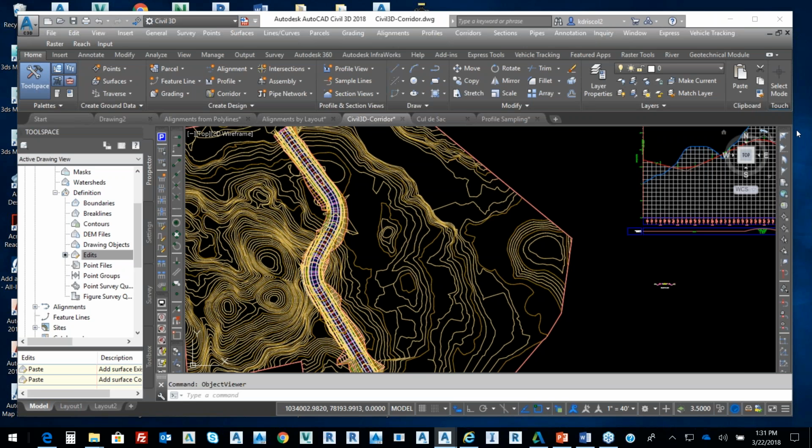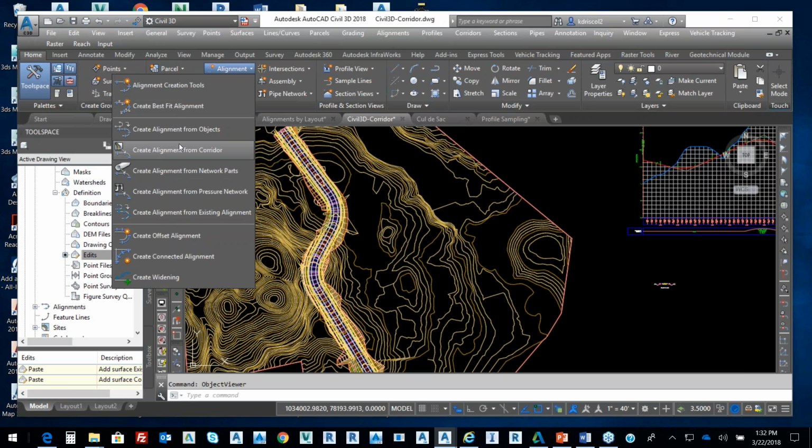This might be the question that you were referring to on how you created that. There was a question on how to create horizontal alignment, not from an object, but manually inputting the curve data. And they say when I said manually, I mean placing the northing, easting, STA, PIs, etc., basically information that we get from DOT PDF plans.